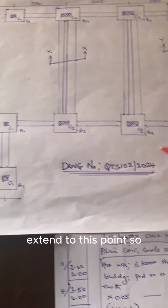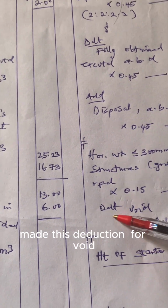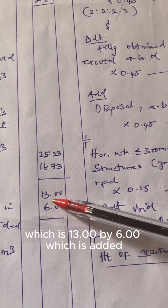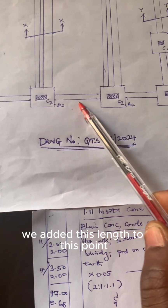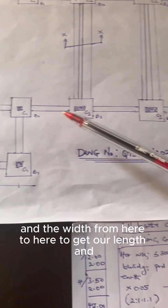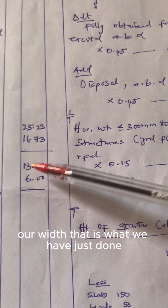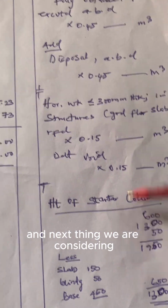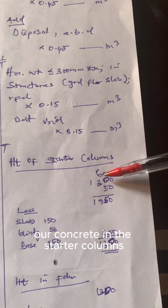Because we took it as a whole, remember that we have a void here, meaning that the concrete slab will not extend to this point. So we're going to make a deduction from what we have established. That is why we have made this deduction. Deduct for void, which is 13.00 by 6.00. How did we get the 13? We added this length to this point and the width from here to here to get our length and our width. That is what we have just done.